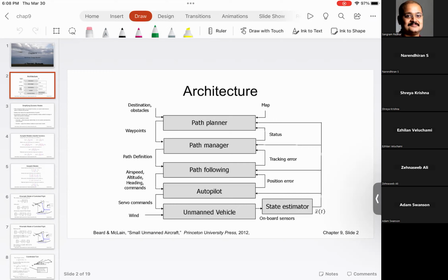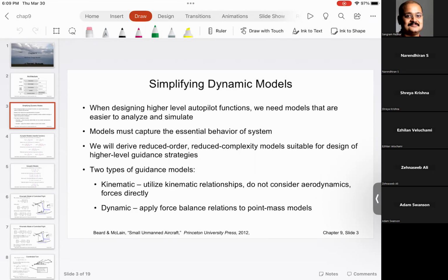So it is exactly the same as the trajectory planning problem that we studied in articulated robots. When we talk about kinematic and dynamic models, kinematic models do not include any type of mass or inertia effects. Dynamic models include the forces, moments, masses, and inertia effects that make that whole system work.